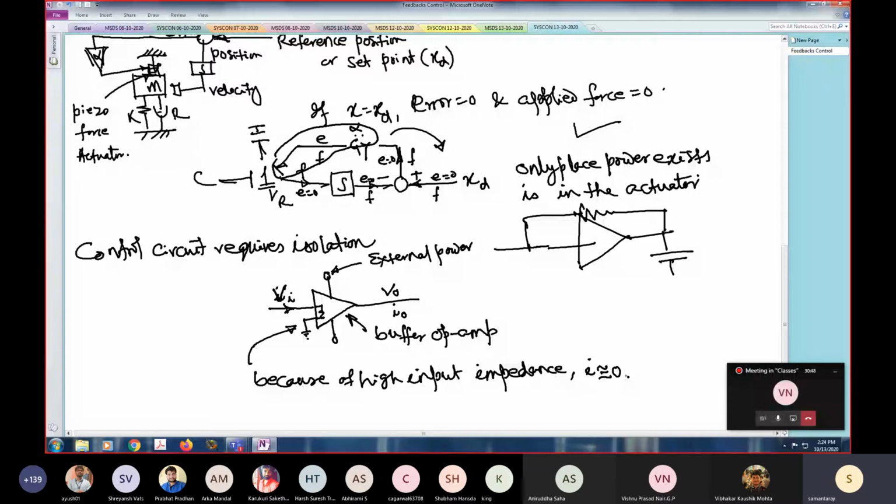All right. So it should be only a signal connection, whereas in practice it is actually wires. We don't connect signals by signals. How do you connect a controller to a system? You will put some kind of wiring. Now through that wire, if you apply a certain voltage, some current will come back. So to isolate that, you have to use these buffer operational amplifiers. Though we will not show them in the circuit, it will be assumed that those buffers are present at appropriate places. All right?